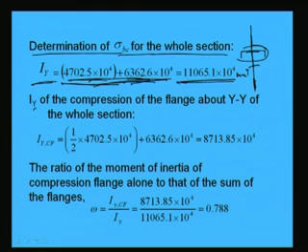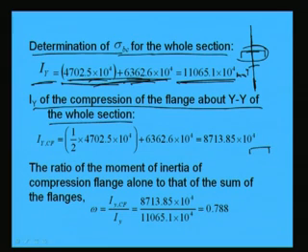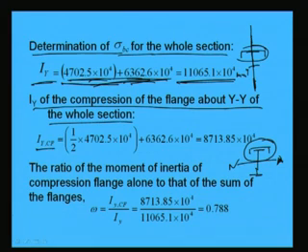Now, Iy of the compression flange about YY of the whole section. Again we will find out the Iy of the compression flange, that is, we know this is the I section, this is the neutral axis. So, we will find out the Iyy value of this compression flange, because as we have seen yesterday, this value is required to find out the stresses. So, Iy in the compression flange will become how much?